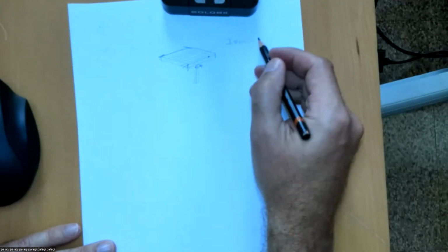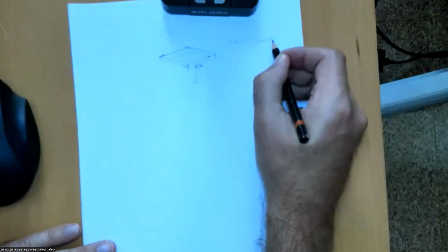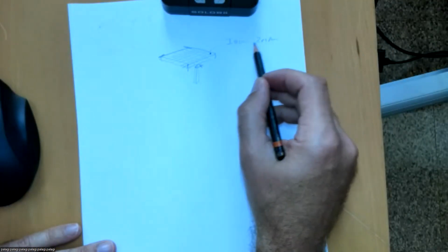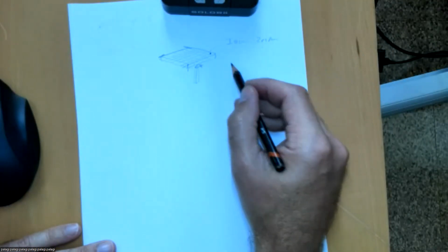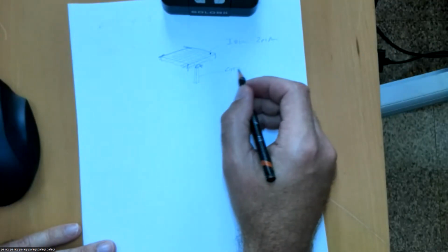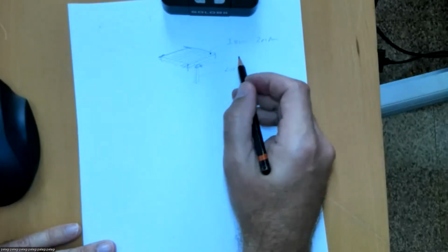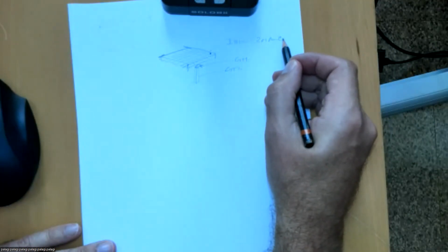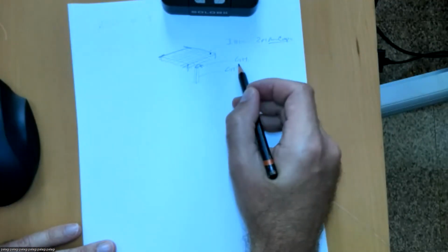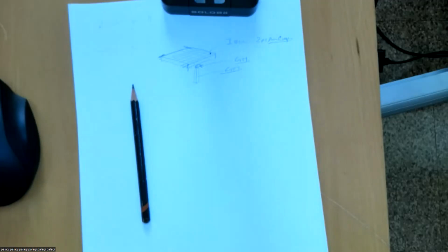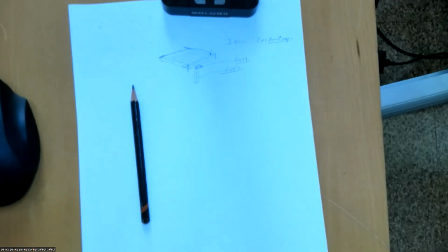So we're going to actually make one of these as a 2-point adaptive, because although this is simple and flat here, we might want to play with it more later. The columns, we're going to make generic models, just straight generic models, but we're going to give them some parameters, the same way with this thing. So we're going to make one adaptive component and then two generic models as a way of putting this together, but also letting us mess with some stuff later.